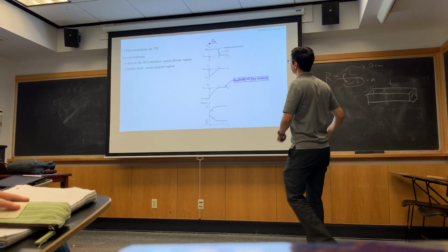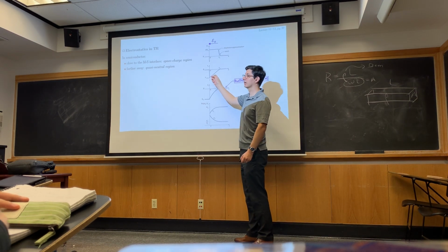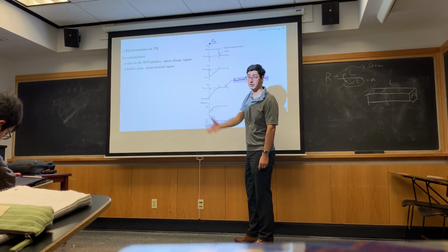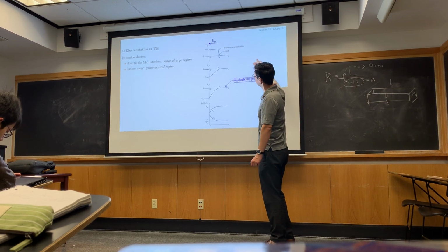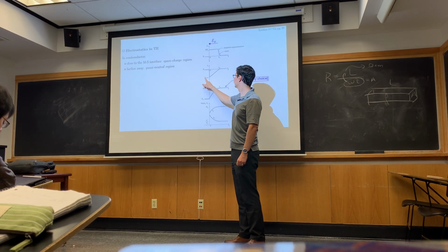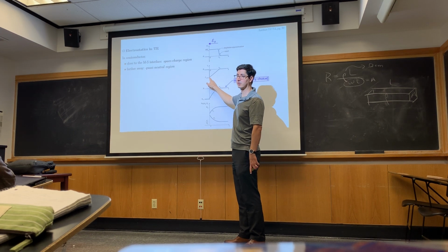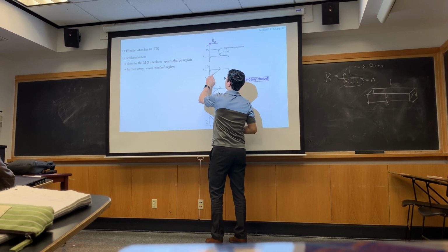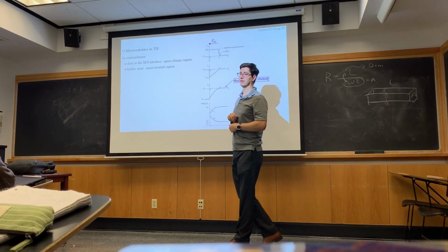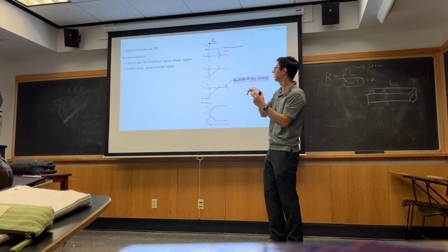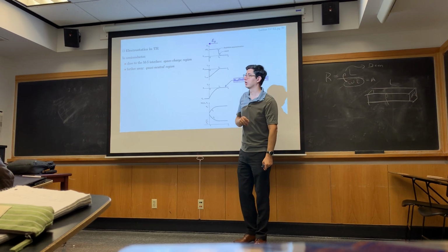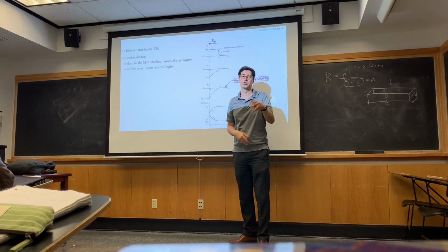Okay, so then we're going to integrate this from the right side, get electric field. We're going to assume from some distance xd, we're going to have to calculate what that is. We're going to integrate from the right. That gives us max electric field at the junction, and then the electric field quickly goes back to 0 when we integrate over this spike. Why is that? Well, the total charge enclosed, when you're integrating, is 0 at that point, so there should be 0 electric field over here.